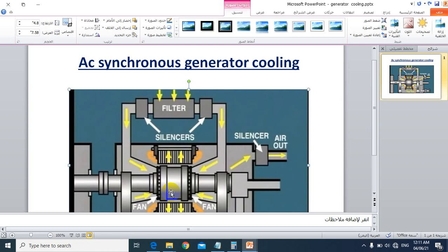It's highly effective, except for machines with considerable axial length. The disadvantage of axial ventilation is non-uniform heat transfer. The cooling is less at the outlet part of the machine because the air in passing through the axial ducts has time to become heated.